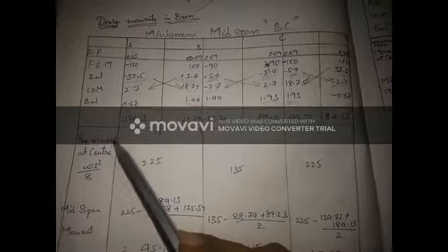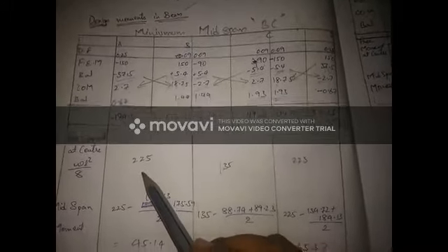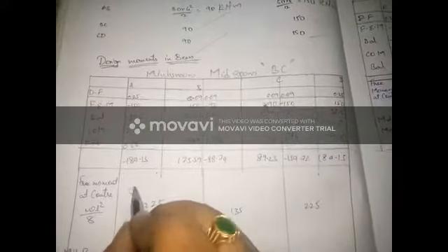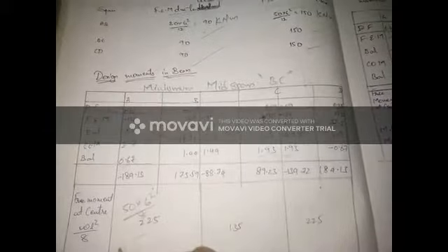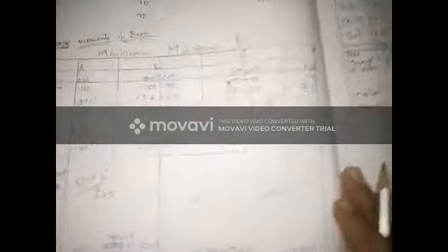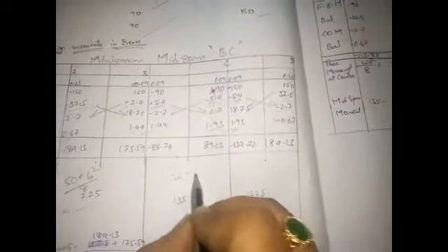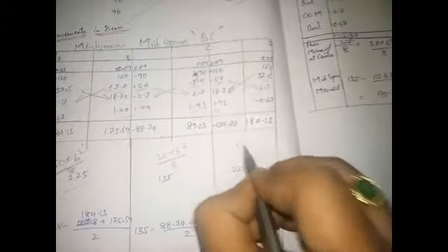So first, free moment, that is with respect to the simply supported condition, we'll take this value, that is WL square by 8. As we know, W here in this case is 50 kilonewtons, that is the total load. It is 50 into 6 square by 8, that will give us 225. Whereas for the midspan condition it is only 30 kilonewtons, that is we will take 30 into 6 square by 8. Here also it is the same, 50 into 6 square by 8.